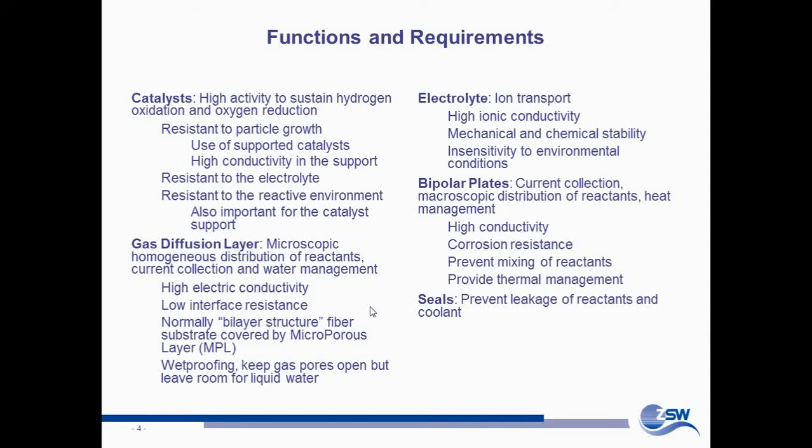Remember, at the anode we've got hydrogen present, we've got water present, and we've got protons present. And at the cathode, we've got protons present, we've got oxygen present, we've got water present. So this is a challenge to any material, and if you ask a materials engineer which materials are good for being in contact with highly pure water, or acid, or steam, the selection is pretty narrow.